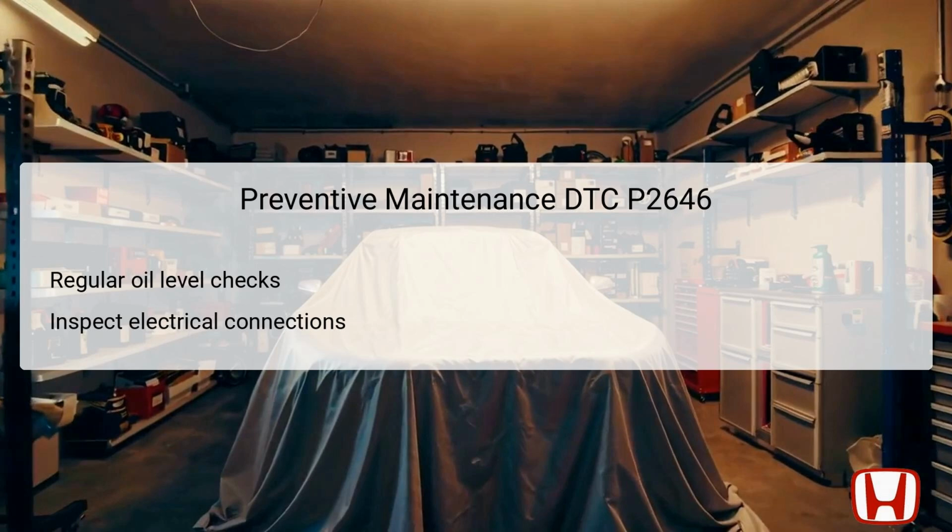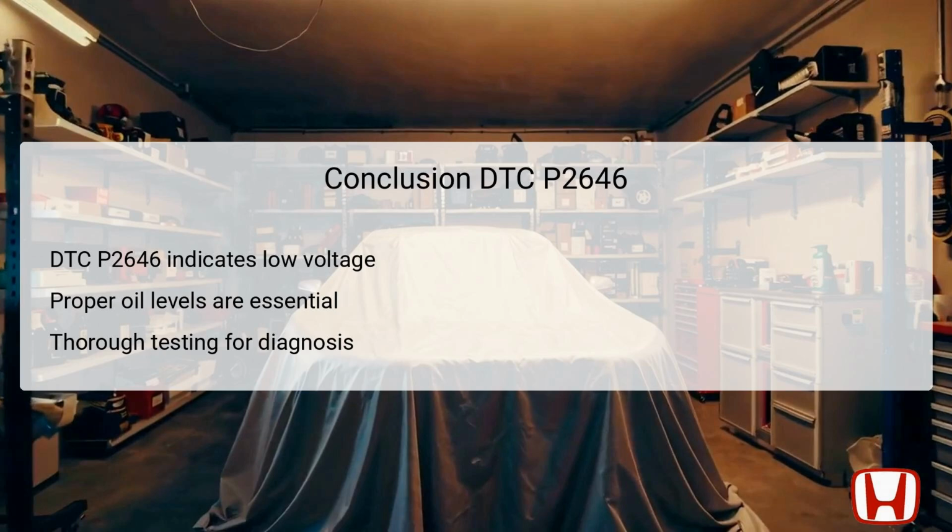Developing a maintenance schedule that includes these checks will be beneficial in sustaining the vehicle's efficiency and avoiding costly repairs. In conclusion, DTC P2646 serves as an important diagnostic code indicating issues with the rocker arm oil pressure switch A on bank 1, specifically highlighting a circuit low voltage condition. Proper engine oil levels are crucial for maintaining the VVT system's performance, as low oil can negatively affect pressure readings and overall engine function. The troubleshooting process requires a systematic approach that includes verifying oil levels, checking electrical connections, and conducting pressure tests with specialized tools.